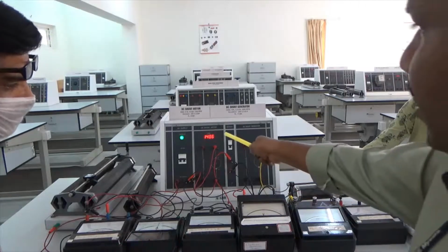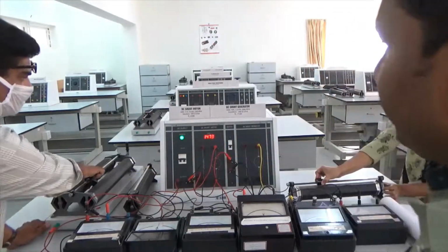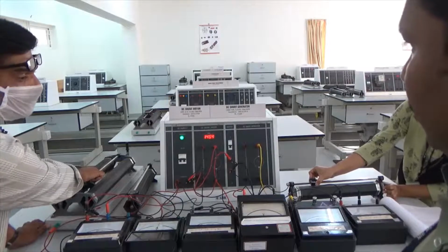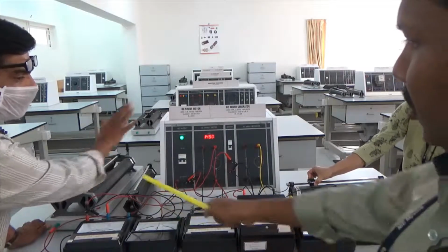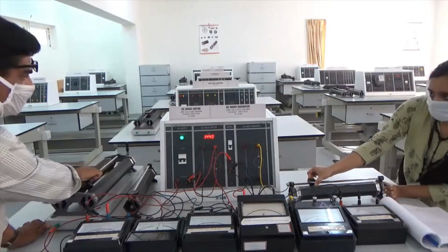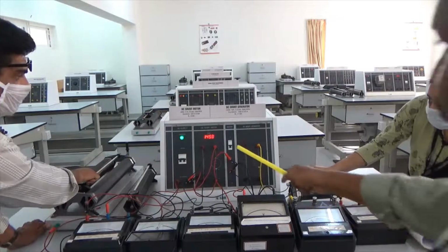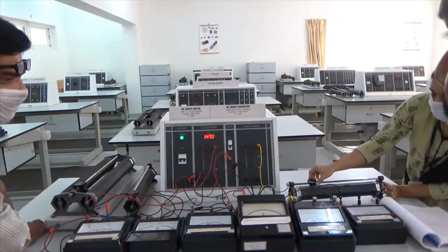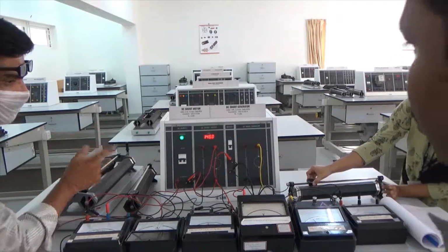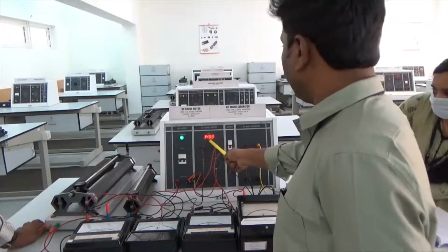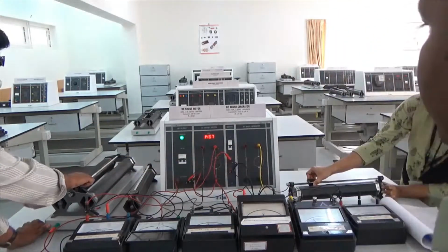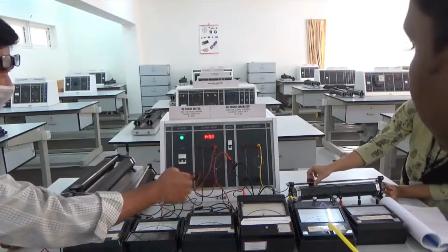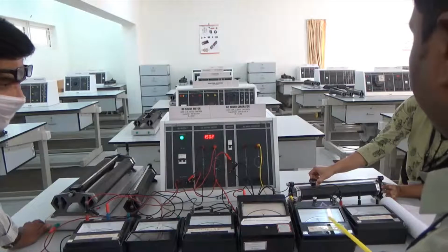Then the speed decreases. You have to maintain the speed by cutting out the starting rheostat. This is a tuning between the starting rheostat and the field rheostat of the generator to keep the speed at 1500. At each step of the reading, you have to note down this constant speed. So now we are making an exercise to bring it to the rated speed by varying the excitation. Yes, a little bit. Okay, now the current starts.